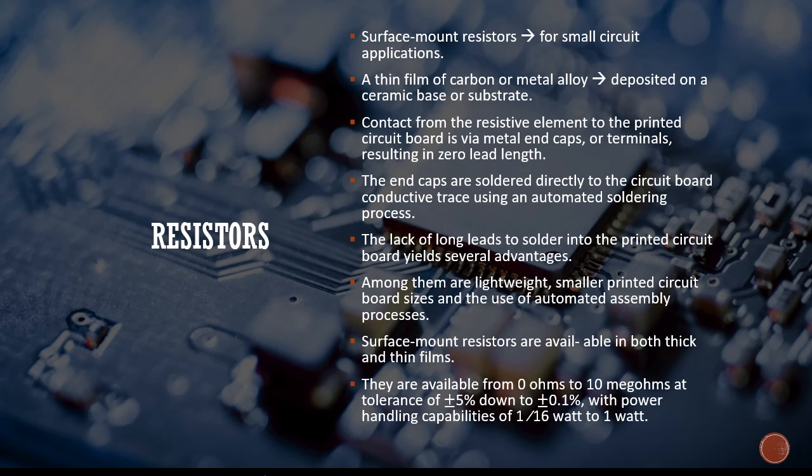Surface mount resistors are available in both thick and thin films. They are available from 0 ohms to 10 megohms at tolerance of ±5% down to ±0.1%, with power handling capabilities of 1/16 watt to 1 watt.